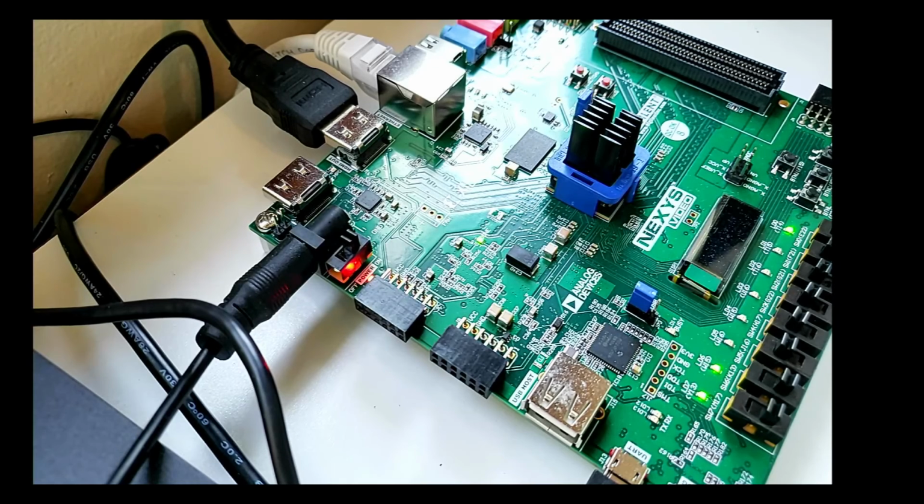If we look back to the inverter example, where we took the switches and we're inverting it to get the LED outputs, that inverter was implemented as a lookup table, which is cool, right? We can implement any logic function as a lookup table. And that lookup table is directly instantiated on the device. We built an SRAM memory to implement that lookup table. That's programmable. That is a cool feature. It's going to be extremely slower than actually mapping an inverter using CMOS technology or just low-level gate layout technology of any type. It's a huge overhead.